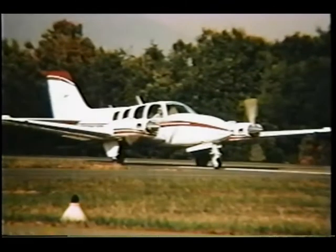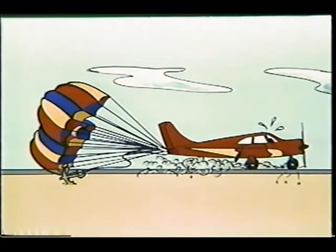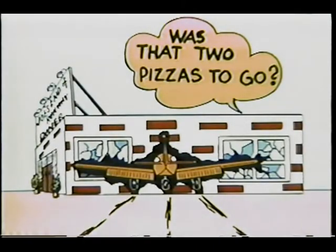Once you touch down, proper braking is the key to coming to a full stop within a specified distance. But since landing performance figures are determined by experienced pilots under ideal conditions using maximum braking with brand new brakes and tires, and since you just might not have quite as much going for you, treat the published landing distances as minimum distances and allow yourself an extra margin.